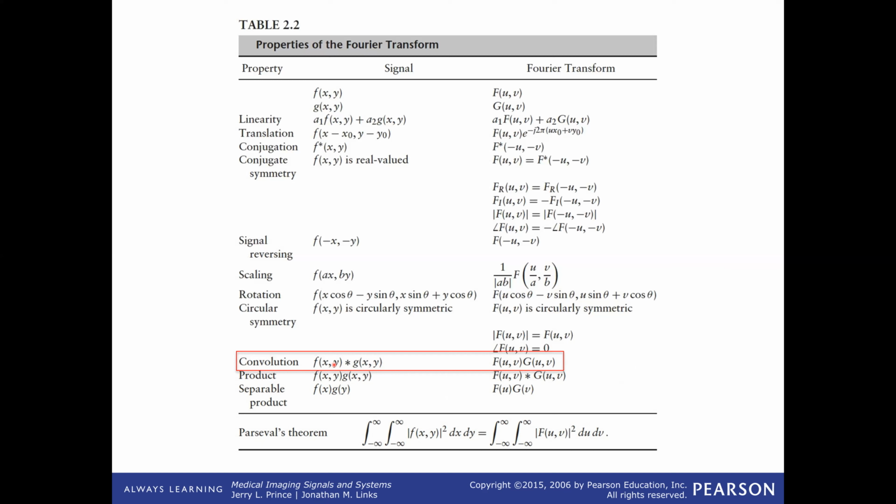When you're listening to audio and there's a lot of high frequency crackle and noise, you can get rid of it by putting that signal through a low pass filter. We're somewhat familiar with that. If there's a lot of noise in a field of view in an image, then we can say, let's convolve it with a Gaussian that has a width of, say, 2.5 pixels. We'll just convolve the whole picture. That'll smooth out the noise. The high frequency noise gets smoothed out. When I look at what happened in Fourier space, I took the Fourier transform of my image and multiplied such that the high frequencies got attenuated. And if there's a lot of noise out there, the noise gets attenuated.